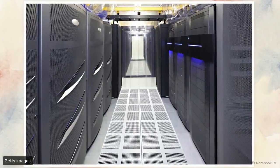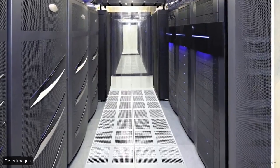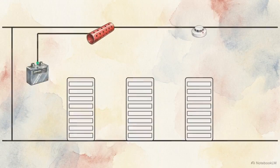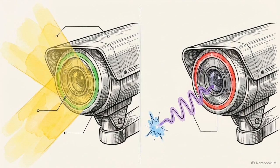Every theoretical concept must adapt to its environment. Data centers, for example, demand aspirating smoke detection. Passive detectors cannot outcompete the high-velocity HVAC systems cooling the server racks, making active air sampling the only way to catch incipient electrical fires. Conversely, petrochemical refineries require multispectrum IR flame detection. In outdoor areas handling volatile hydrocarbons, ignition is instant. The system needs to ignore sunlight and process heat, triggering suppression the millisecond a specific carbon dioxide radiation band appears.